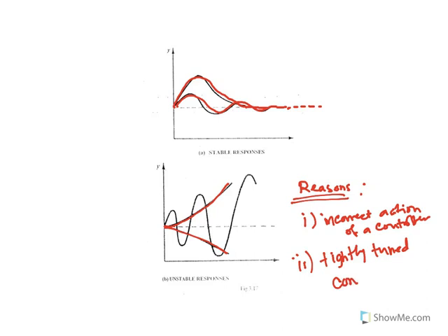That means we have to do some tuning again for the parameters. Sometimes it is either a large gain, or a too small integral time, or a too large integral or derivative time.